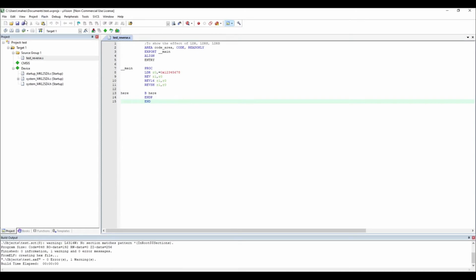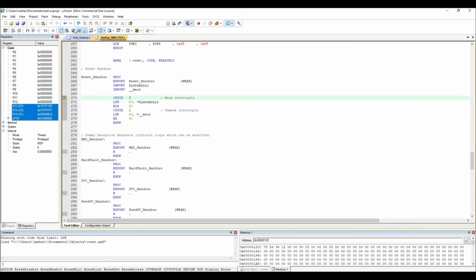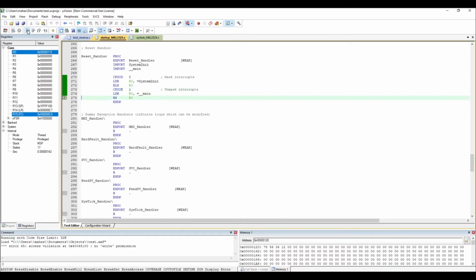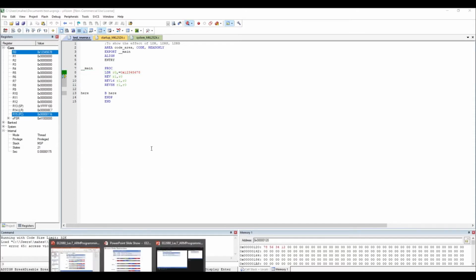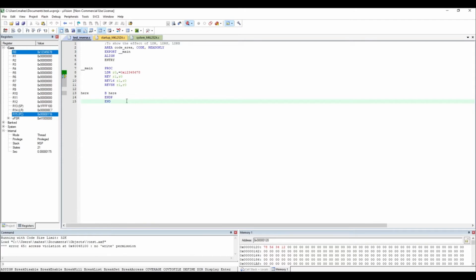Okay, this is the case. All the things I've written here are quite straightforward, so let's do that. I'm loading a value, 1 2 3 4 5 6 7 8, so it's easy for you to understand. The first step is reverse R1, R0, which means the entire word will get shuffled. How does the shuffling happen? Byte 12 will become the least significant byte, and 78 will become the most significant byte. Then 34 and 56 will get exchanged. You can see it over here.